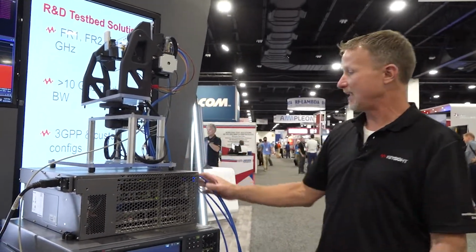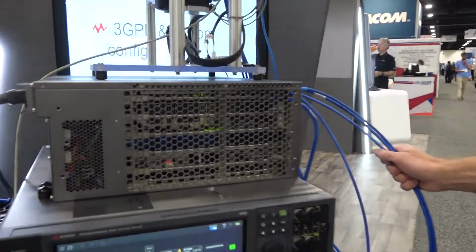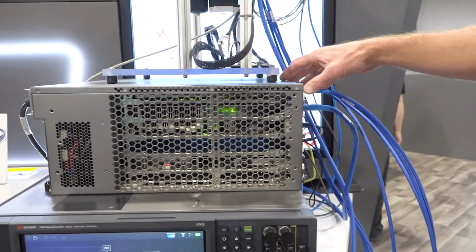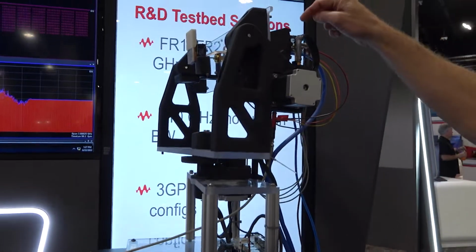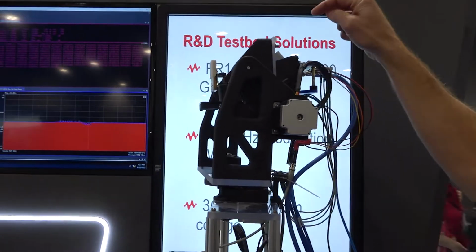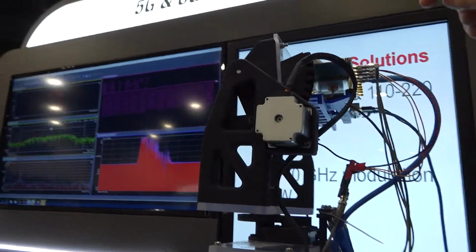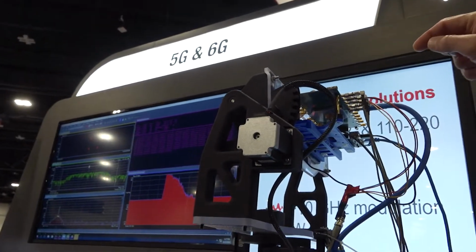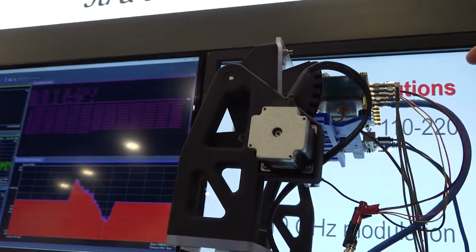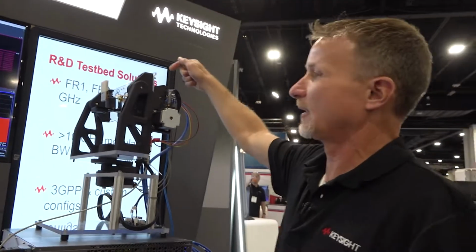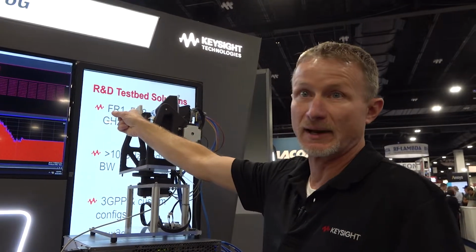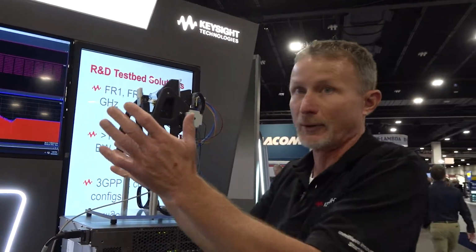In this demo, we're taking the baseband IQ out of the arbitrary waveform generator and running it into the device under test. The device under test in this case is a Nokia radio on glass solution that we're generating a signal in D-band at 141 gigahertz. That comes out of the radio on glass and goes through their phased array antenna. So this is actually forming a beam.